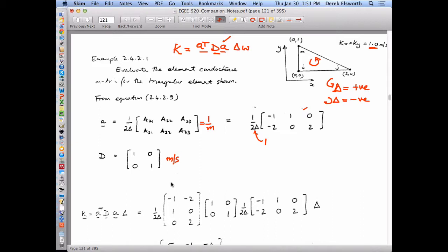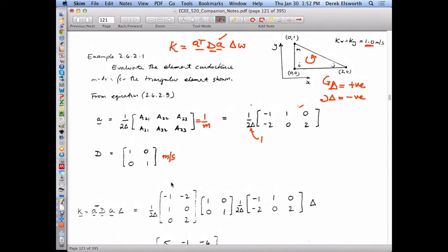The other thing to mention is that, we mentioned that most finite element codes not only allow you to do 1, 2, or 3 dimensional problems in the same code miraculously. It's because of this indexing, but also they usually don't prescribe material properties. So your units just have to be dimensionally consistent. You need to choose a unit for length, meters, a unit for mass, kilograms, and a unit for time, which is seconds. As long as you are consistent with that, you'll be fine.